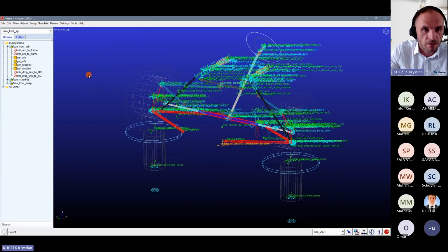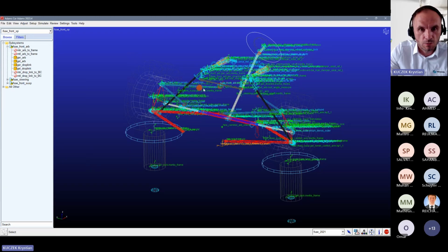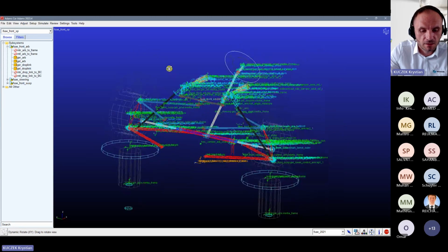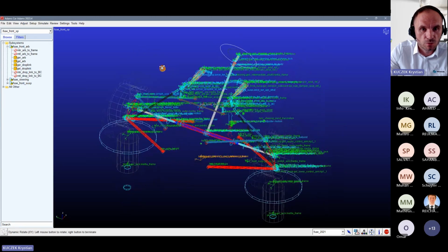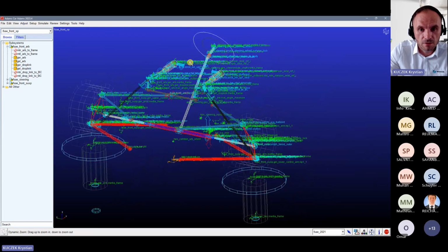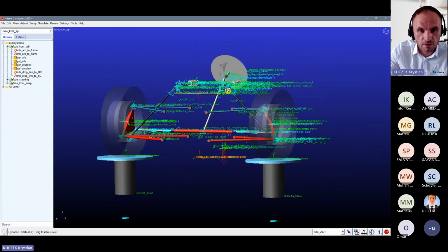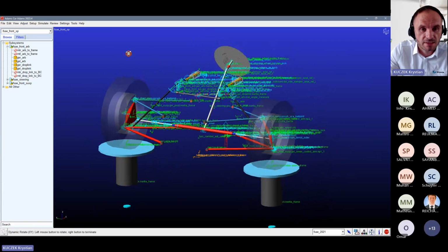As I said, by right click, just like here, you will also get the help about how to navigate, rotate, and zoom our model with the T, Z, or R keys. You will be able to rotate your model, translate your model, or even zoom your model. With Shift S, I would like to change the transparency mode from wireframe into shaded mode, for example.